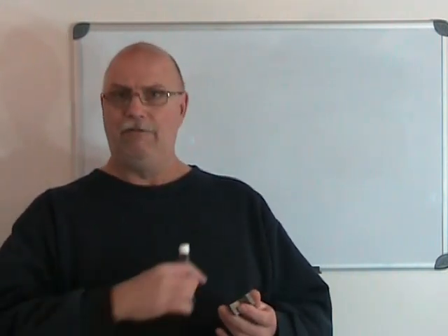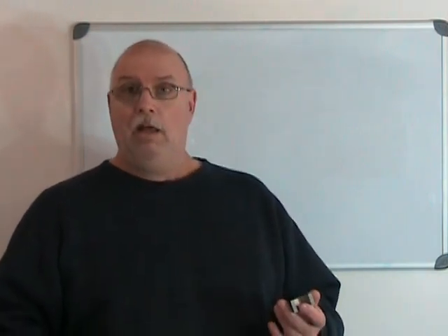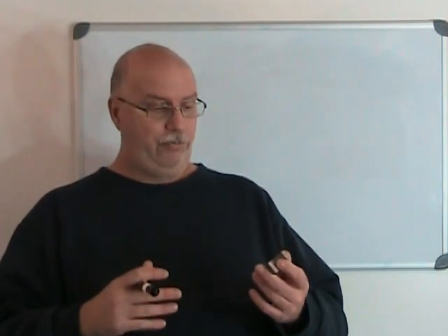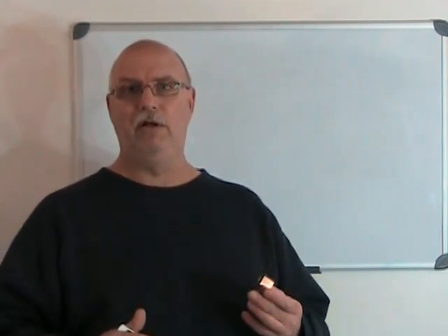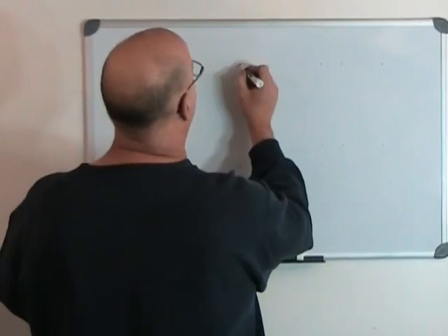Now, for our sketch, we're going to go at it one step at a time. Instead of trying to draw it final right off the bat, we're going to draw, erase, and detail. And for that, we're going to first start by laying out our general shape of the part. And that means, what are its major dimensions in the three views? And we're going to do a front, right side, and bottom view in this case.